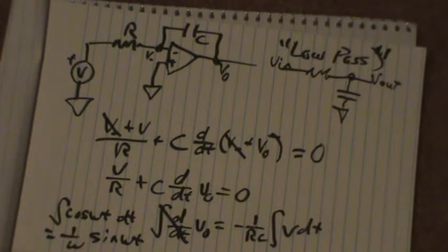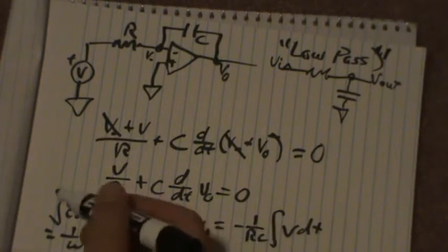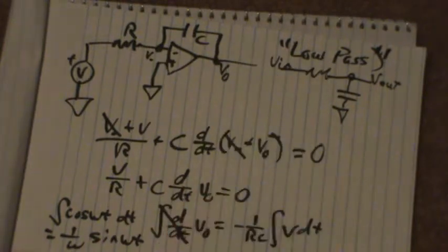So low frequencies go through fine. As I go to high frequencies, omega goes to infinity, 1 over omega goes to 0, so high frequencies get killed. So integration has to be a low-pass filter, and that's what this does. So yippee skippy, you now have another circuit to add in: an integrator if you want to treat it mathematically, or a low-pass filter if you want to treat it signal processing style.